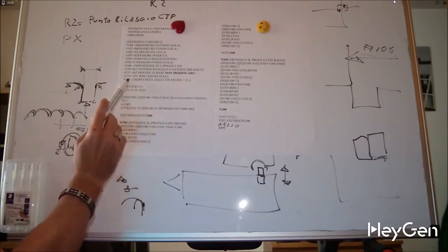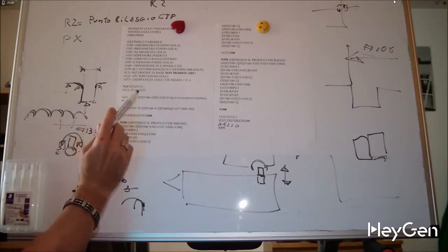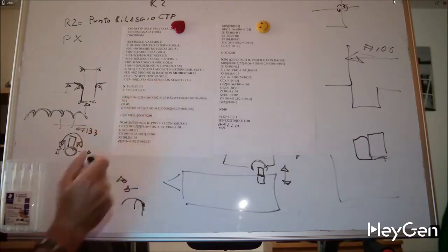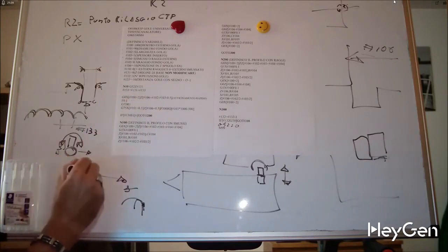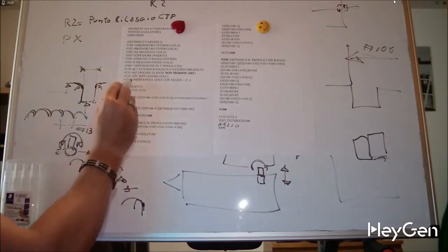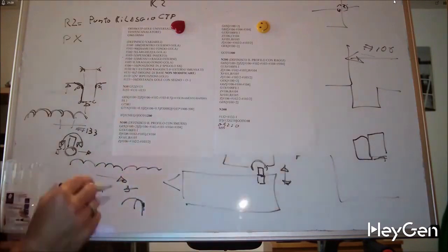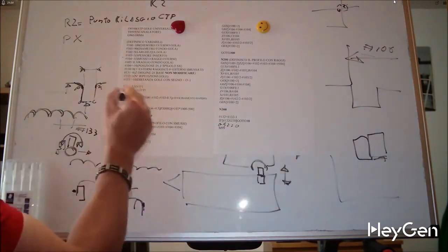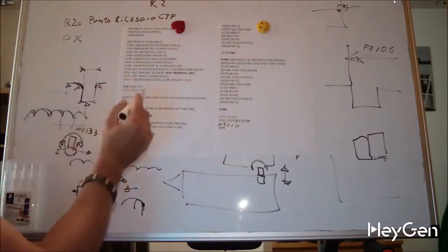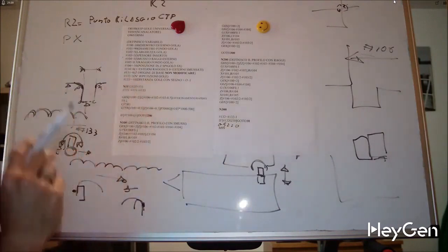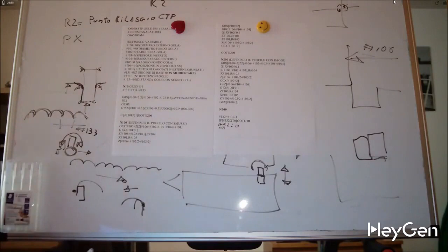Which becomes less for the algebraic formulas. So minus 10 this distance, because I can make the grooves in one direction or the other. So if I didn't put minus here, but put plus, I would have made the grooves from the spindle towards the tailstock, and I'm already shifting my origin. Actually, I'm not shifting the origin, I'm shifting the value that I'll assign the origin instead.